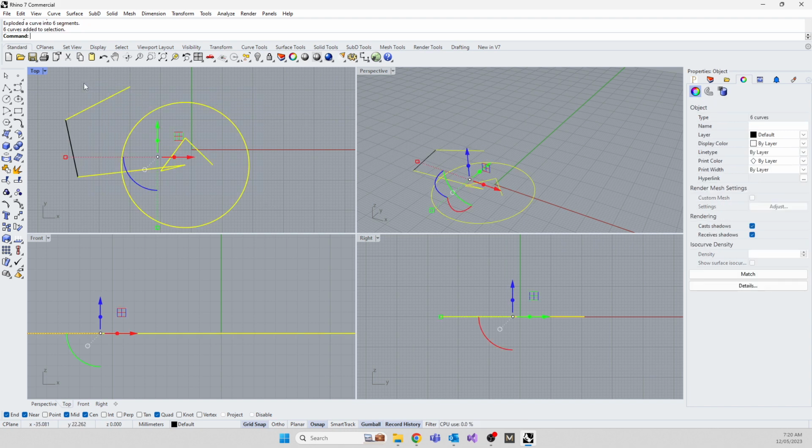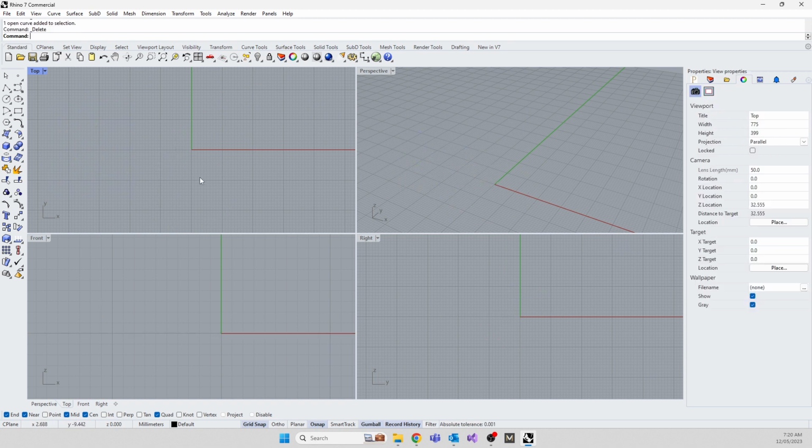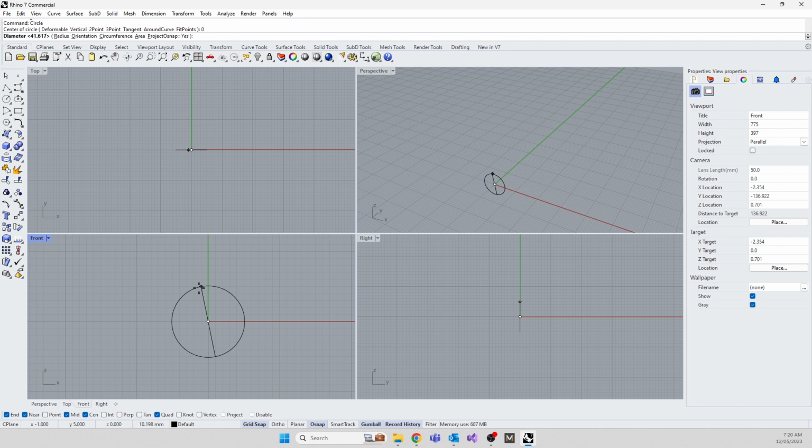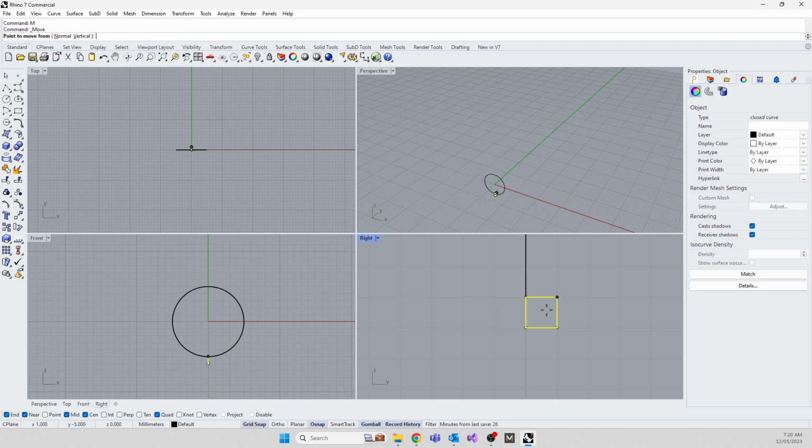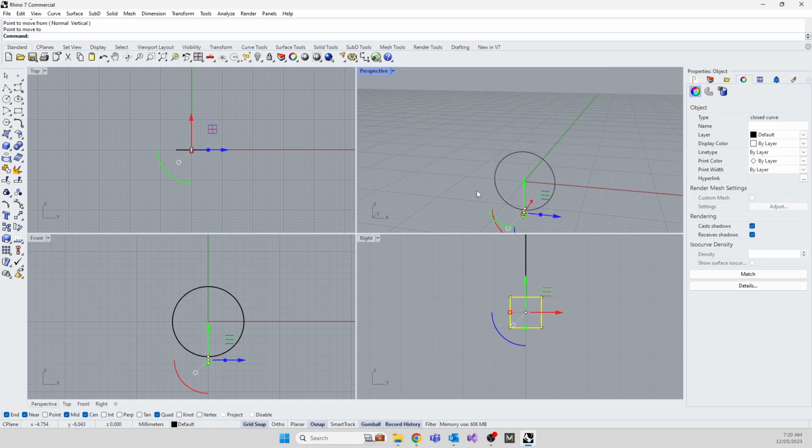All right, that was one little part about housekeeping. Now the other one is creating constructs you can save. So with history on, create a circle from 0. I like to make it exactly 10, and I'll show you why. My grid snaps on. And then I like to make a little profile on the end, whatever that profile may be. Let's say a square over here, and I like to make it exactly 1. I'm going to turn grid snap on, move it from the middle of that to that, and do a sweep 1.